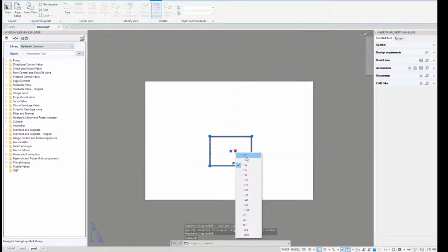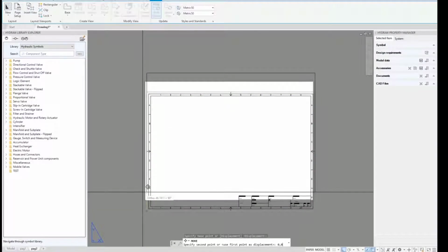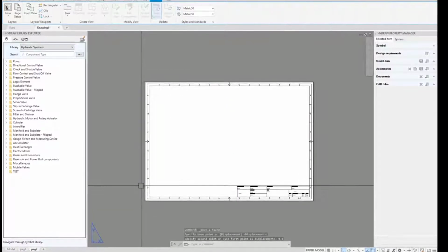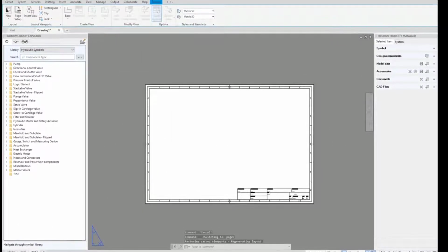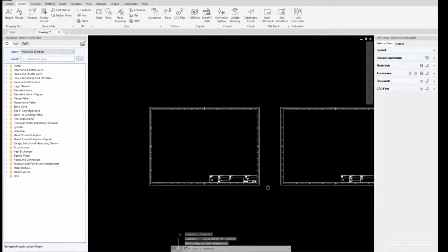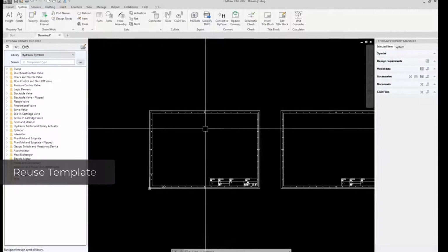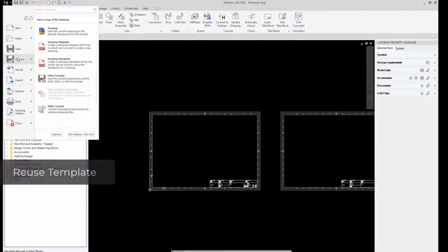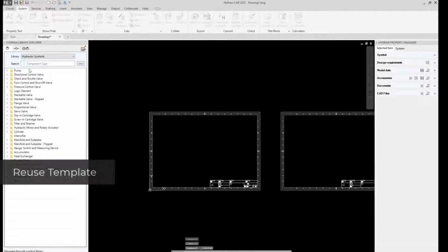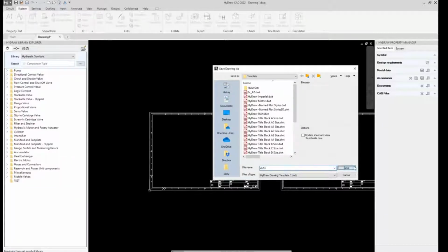The scaling will be 1 by 1, and again, I can move wherever I want. 0, 0, so it goes directly to the origin. So now that I have prepared my document, page 1 and page 2, and in the model space, I have everything ready to start. Of course, if I want to reuse this in the future, I can just do a file, save as, drawing template, and here I could save it as 2 pages A3. So then next time I can start from here.